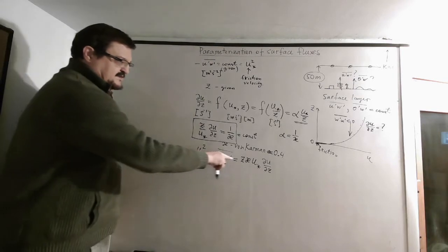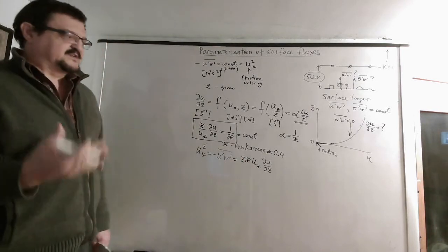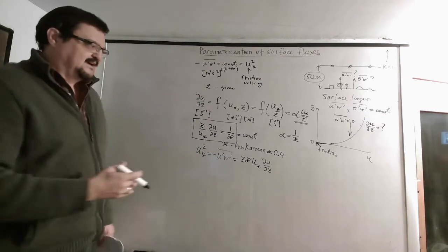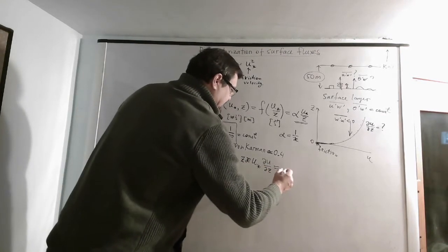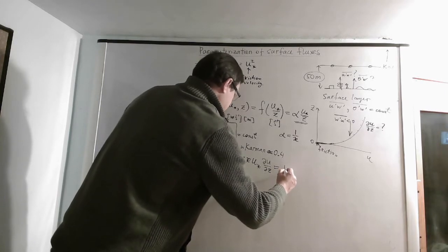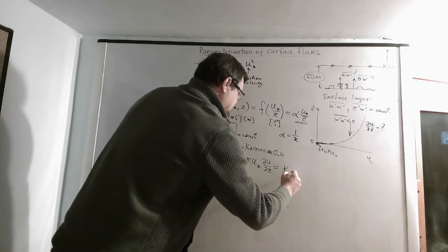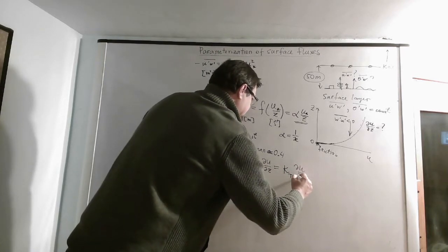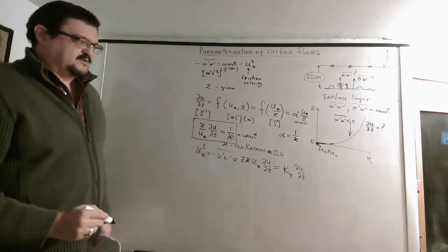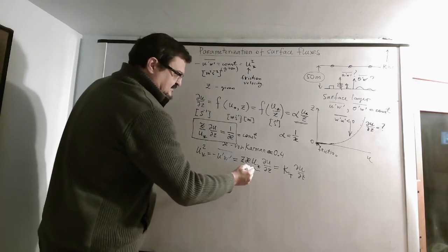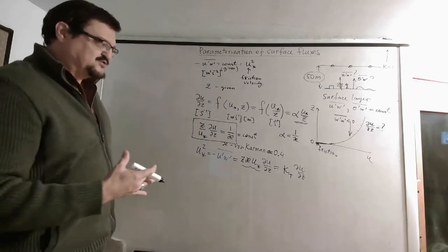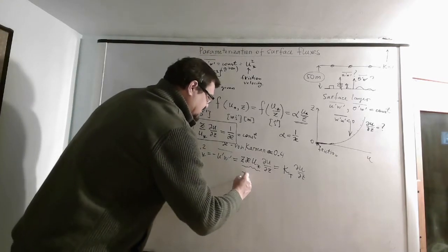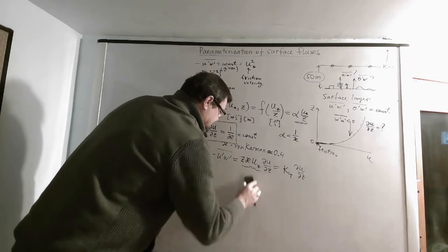So this is flux equal to this, and remember last time we introduced the so-called eddy or turbulent diffusivity, which was a K times this turbulent du dz, from which we conclude that our K, this turbulent diffusion coefficient in the surface layer, is proportional to height.